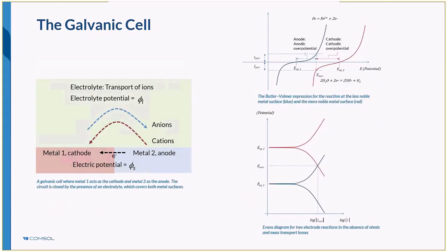If we look at a galvanic cell, we typically wish to represent the electrochemical reactions on a current density basis. This allows us to examine where the rate of corrosion is most significant and how fast the material is corroding. The representation of these rates can be achieved using electrochemical kinetic expressions to relate the overpotential, that is the driving force for the corrosion process, to the current density.